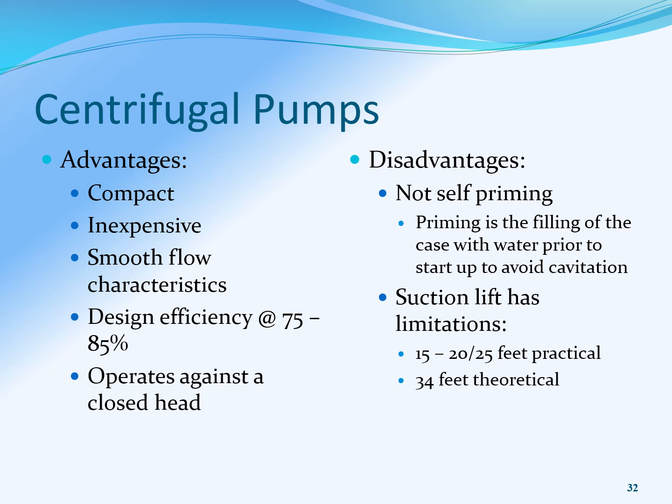And so it's important that you prime these, which means, if you don't know what priming is, it's where you would fill it with a liquid to push out any air, so that way you can avoid cavitation. If there's cavitation, then there's no liquid in those areas, and you're not going to be able to pump anything.